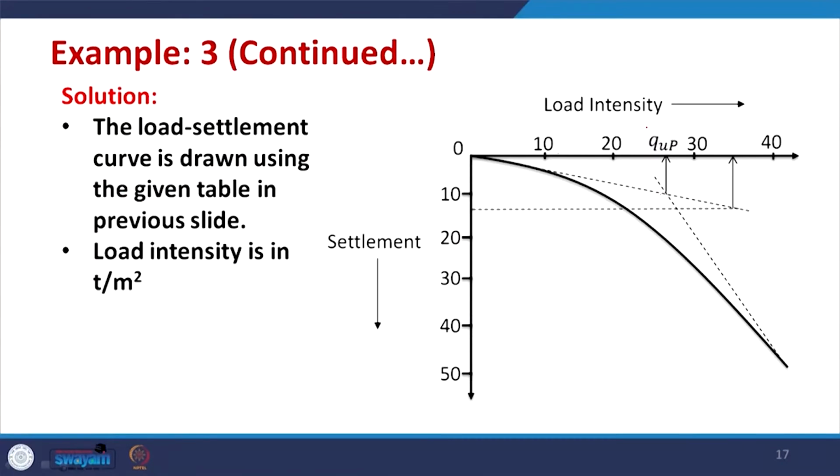Now, for this 12.8 mm settlement, we determine the load intensity using the method suggested by researchers. In this case you use this chart back again. In this chart, for 12.8 mm settlement, we cannot use this curve because it is out; for 12.8 mm, your curve is out.